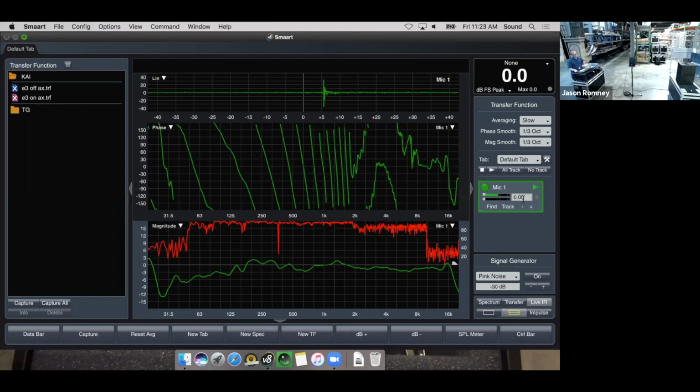And the sound that is hitting the microphone is happening, we think, probably around 7 milliseconds later, right? Just based on our little guess here. So what I could do is add 7 milliseconds of delay to that reference channel, which would back it up to line up closer to where the mic is.